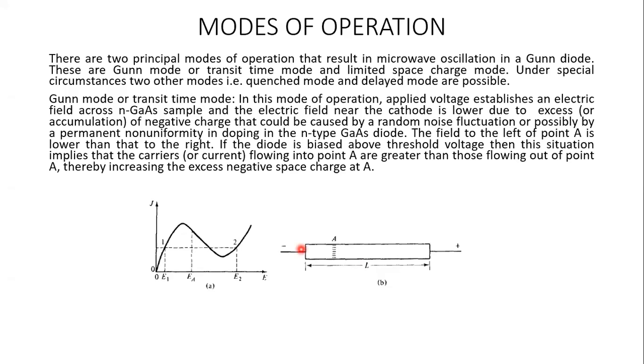And since the electron, as we just discussed, has two different valleys, the electrons are jumping from the lower valley to the upper valley if they are getting a sufficient amount of energy. That is another reason why it has a different name: transferred electron devices. Electrons are transferred to the other valley, the upper energy level. Sometimes it is also called hot electron devices, because the energy level of the electrons in the upper valley is very high.